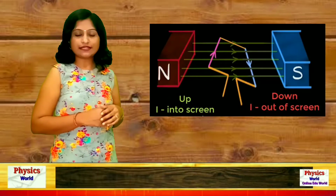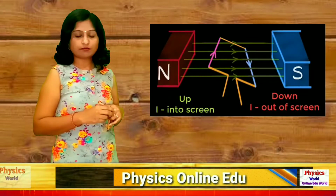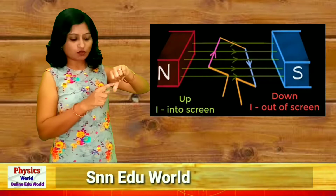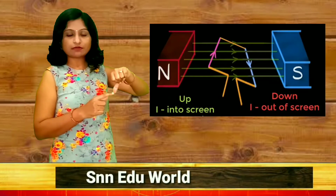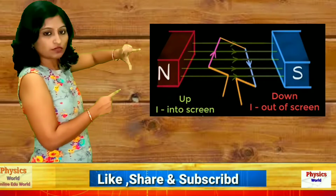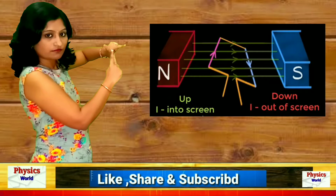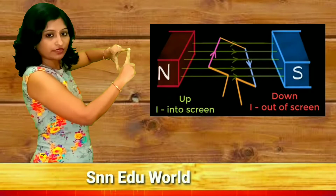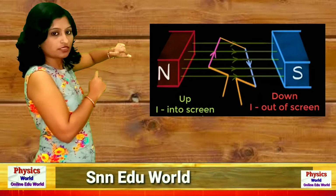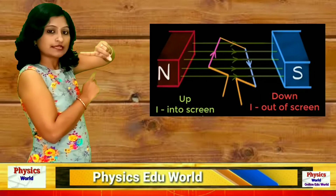Similarly, the second side moves in the downward direction, but the direction of the magnetic field is the same. So the motion direction is downward, but the magnetic field direction is the same. So we have to show like this: coil direction, magnetic field direction. So these four fingers will represent the direction of the current. So the direction of current is coming outward to the screen.